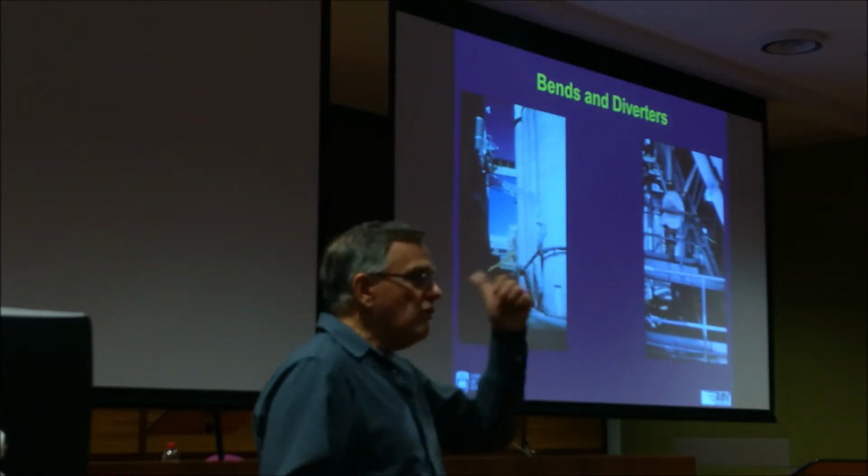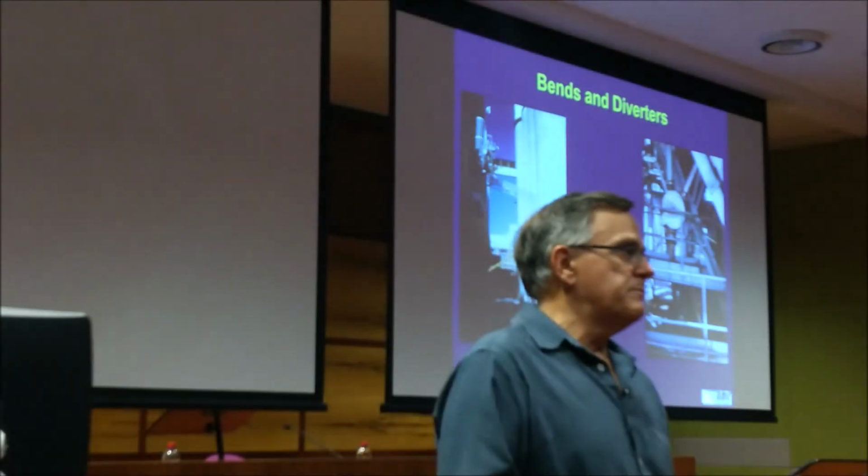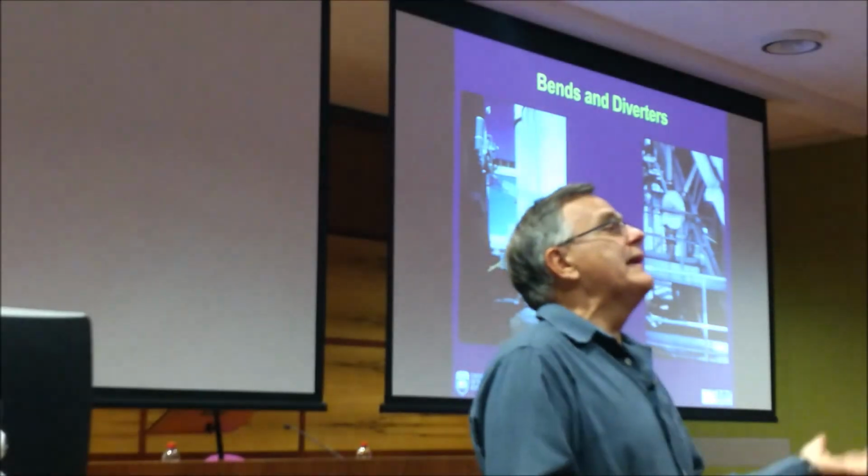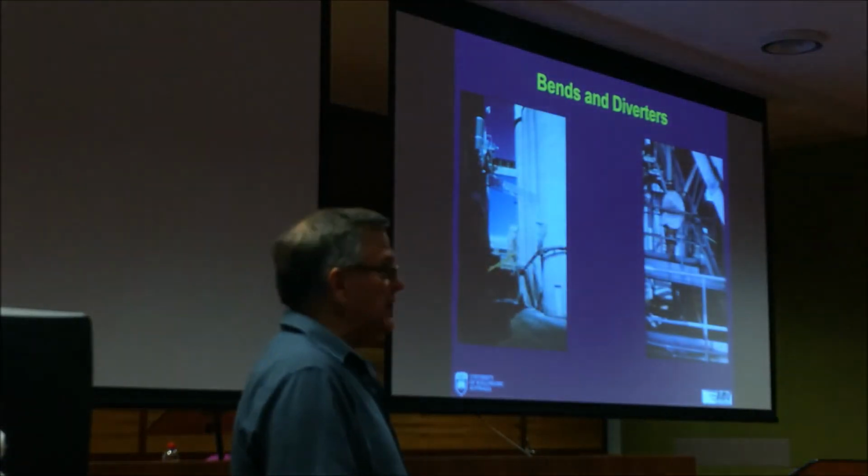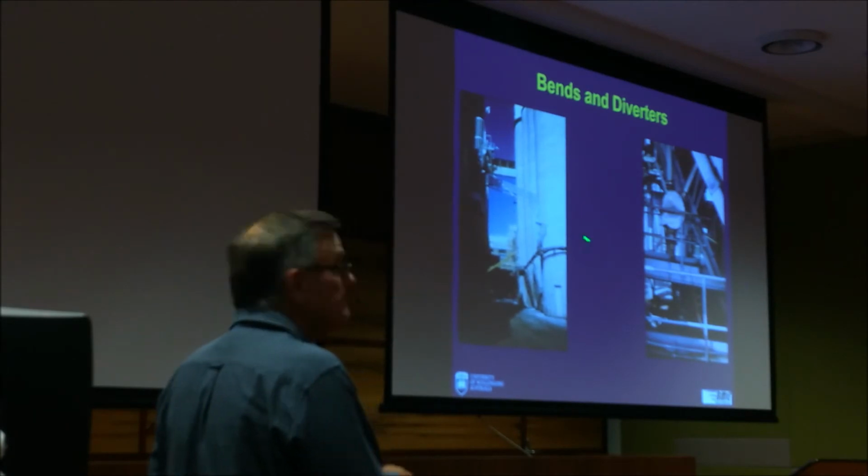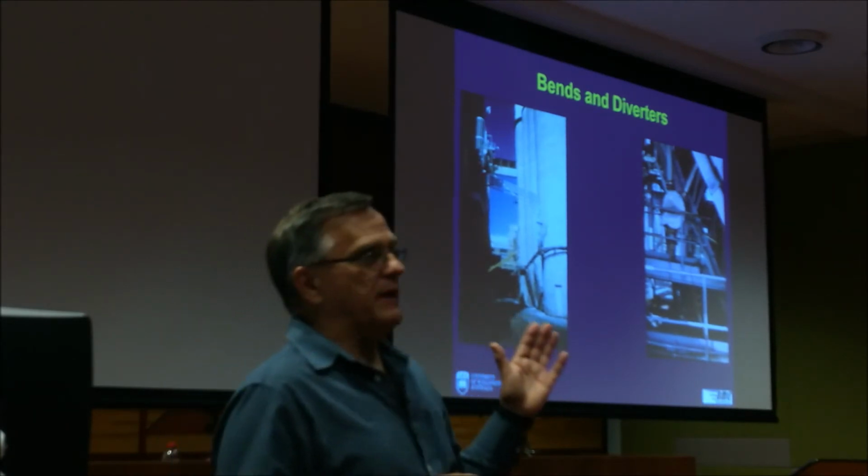So my general golden rule of thumb here is minimize the number of bends. They give you flexibility, yeah, but you can overdo it, so be careful. And also, T-bends will give you a higher pressure drop than a radius bend.